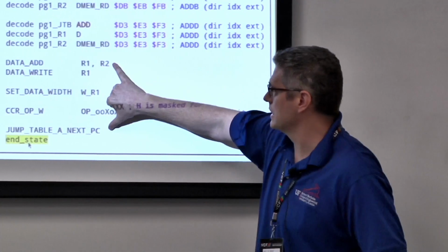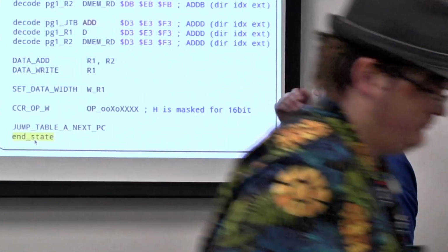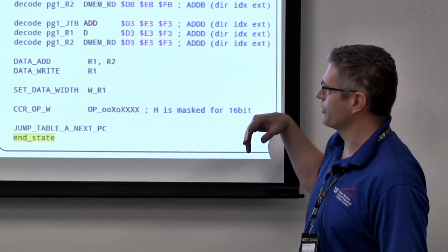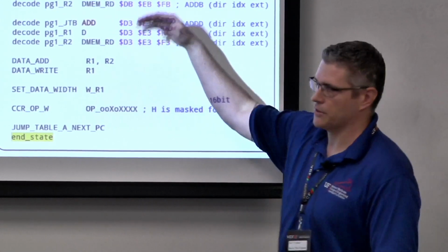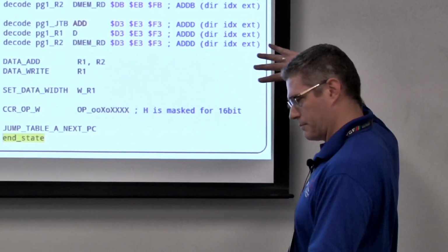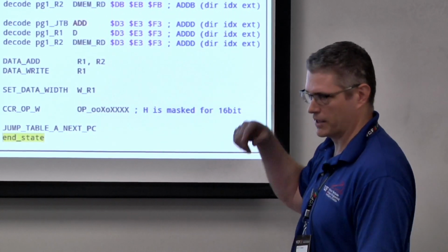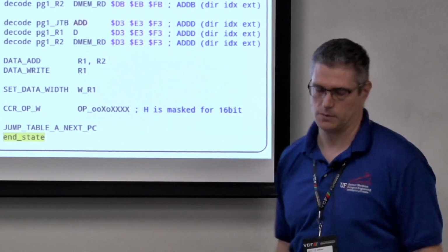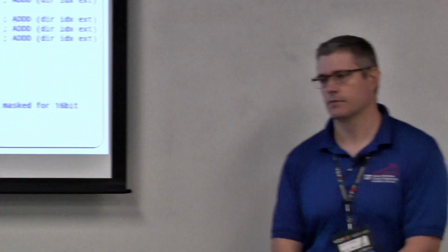This all goes at the speed of the ASIC. In fact, this part here is the only sequential part of this. This is what's actually going to be assembled in the microprogram word, and then all these go into the other decode tables that are in parallel. It's not just 1 microcode ROM. We have effectively 16 microcode ROMs. So that's 1 micro program counter step.